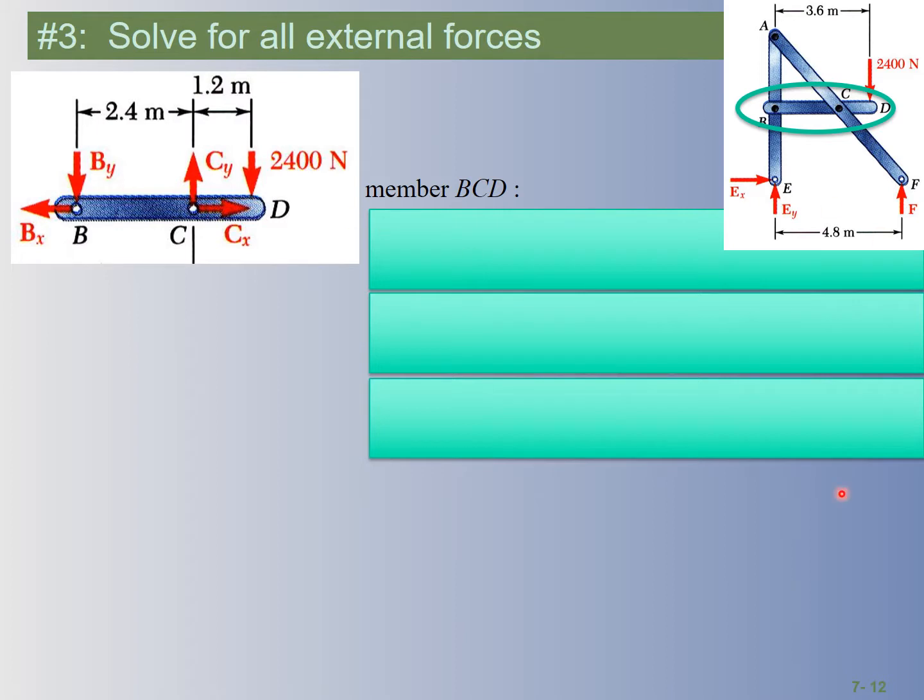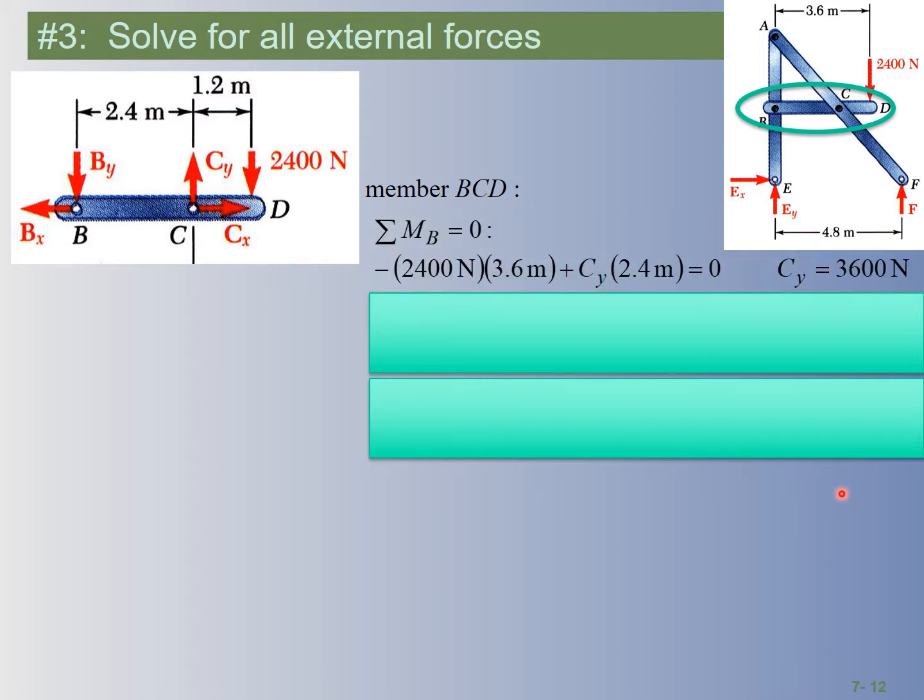So we can start walking through all of these free body diagrams. So let's start with this horizontal beam here. So what could we do? Remember, starting with moments is usually the best way to start with these problems. So here is, and we could have taken the moment around C or around B. It doesn't really matter at this point. The X component of the force, X does not contribute to the moment around B. See how X is pushing and pulling but not rotating.